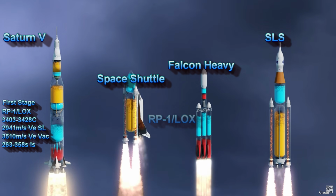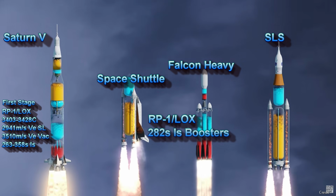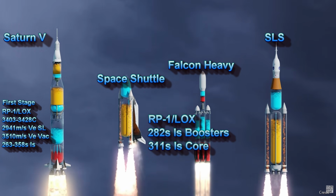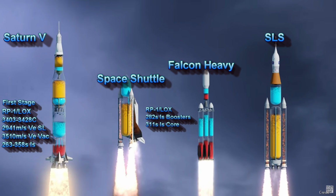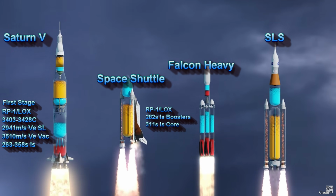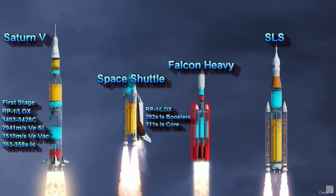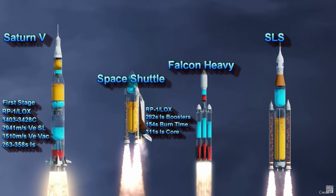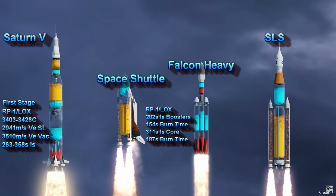The Falcon Heavy is also burning RP1. It has a specific impulse of 282 seconds for the boosters, and 311 seconds for the core stage. These two are optimized for thrust, to get the rocket system out of gravity drag. This one is optimized for high-altitude flight, throttling back until these two fall away. These will burn for 154 seconds, while this one will burn for 187 seconds, 33 seconds longer.